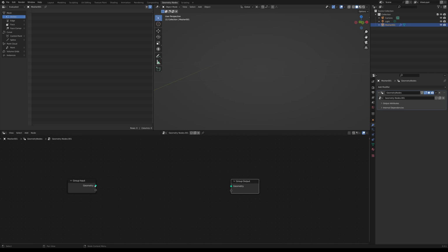And we want to select those very steep vertical areas that have those stretched faces. So an easy way we can do this is take our geometry node here, connect it to a separate geometry node, and we're going to separate geometry nodes based on this selection here. And we're not going to separate the points, we're going to separate the faces, or select the faces based on a condition, and that condition is going to be, I'll add a node, a normal node,